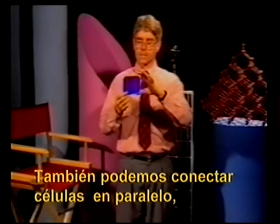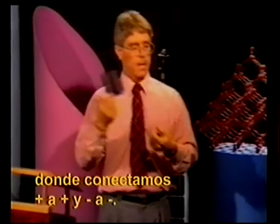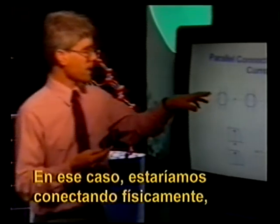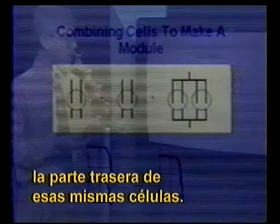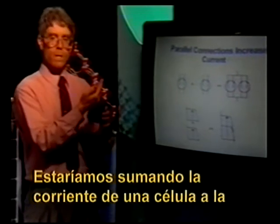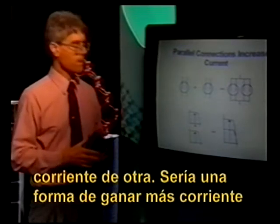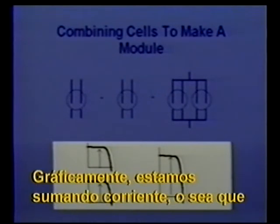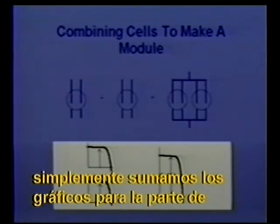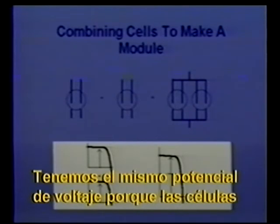Now, we can also connect cells together in parallel, where we connect plus to plus and minus to minus. In that case, what we would be doing is physically connecting, let's say, the fronts of some cells together and the backs of those same cells together. What we would be doing is then adding the current from one cell to the current from another cell. This would be a way to gain more current than you get from one cell. Graphically, we're adding up current, so we simply add the graphs current-wise. The graphs grow up. We have the same voltage potential because we have the cells connected in parallel, but we add up the current that we could get from cells connected together.